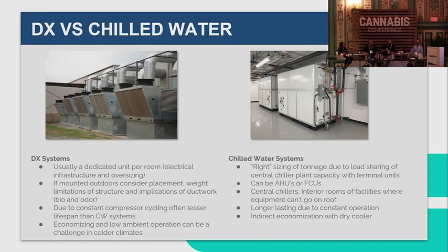Again, you wouldn't have any redundancy, but pipe it over, or it'd be more than 50 because you've got some nights off dehumidification load. But 70 tons or so that you can share back and forth, so you've got less overall installed tonnage. Or you could look at putting in a standalone dehu to handle that nights off, and that's kind of where I was going to ask you, Randy.